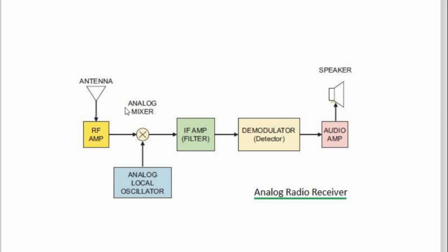In fact, it is not. It is separating the radio frequency and converting that radio frequency into the corresponding intermediate frequency. But here it is called a mixer, doesn't matter. And to that mixer, the local oscillator's frequency is applied, because without that frequency of a local oscillator, you cannot generate the intermediate frequency corresponding to the radio frequency caught by this antenna.